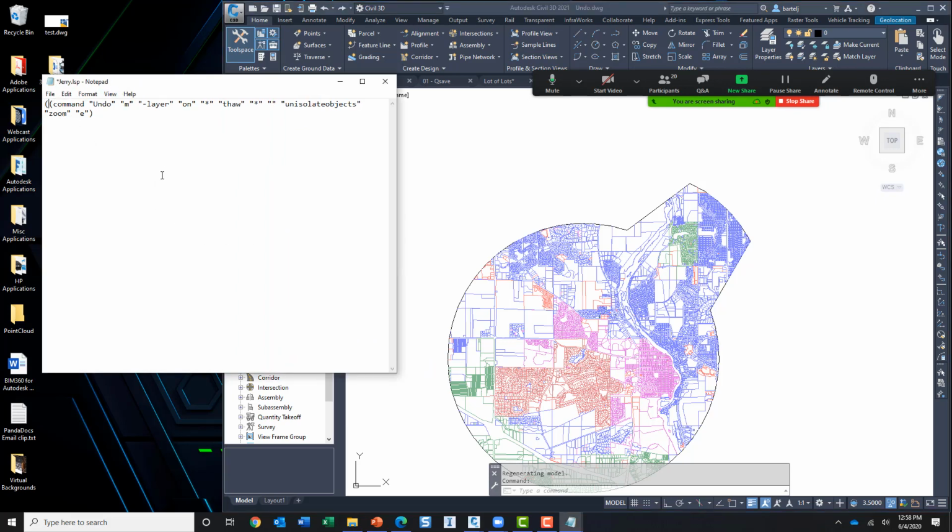So let's do this. I'm going to say defun, which means define function. I'm going to say C:, for something I can type at the command line, and my command is going to be on. And then I'm going to say open and close parentheses, because that's for parameters, and I'm not using any of those. Then if I want to suppress that nil from being displayed at the end, I put in PRINC. That will take that out.